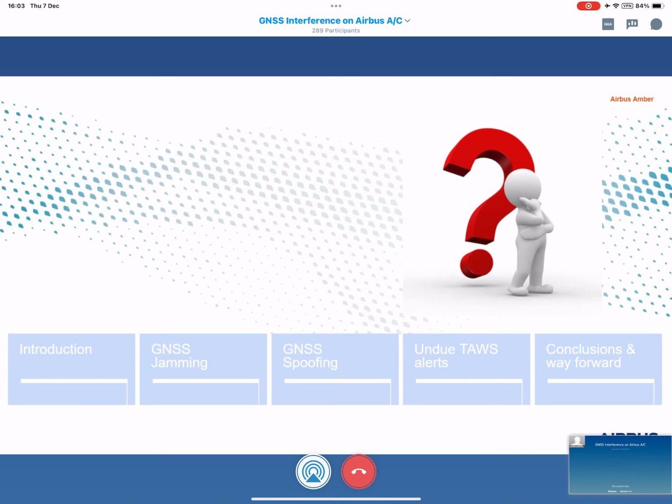However, please keep in mind that the GPWS basic modes remain available. Thank you. Next question, could Airbus change the algorithm for TAWS not to rely on GPS altitude when GPS position is identified as spoofed and disregarded by ADIRS in order to avoid the fault-driven alerts?